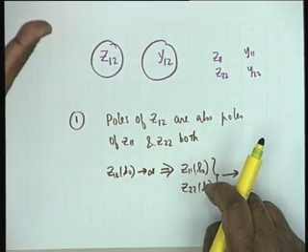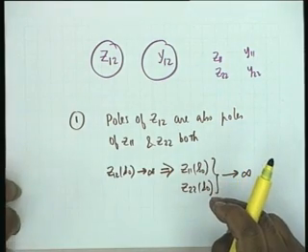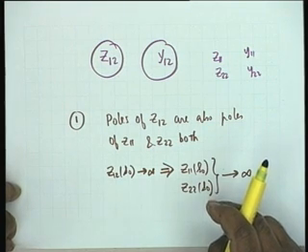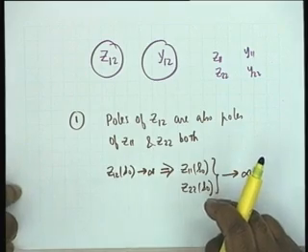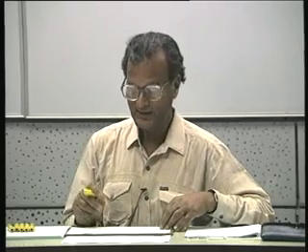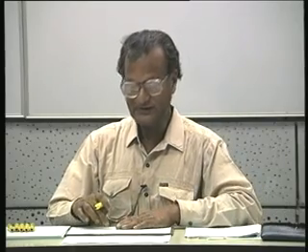And a simple counter example. If both z11 and z22 have a pole at a certain point, it is not necessary to have this belong to z12 also. Not necessary. In addition, z11 and z22 themselves can have independent poles. They don't have to share a pole.